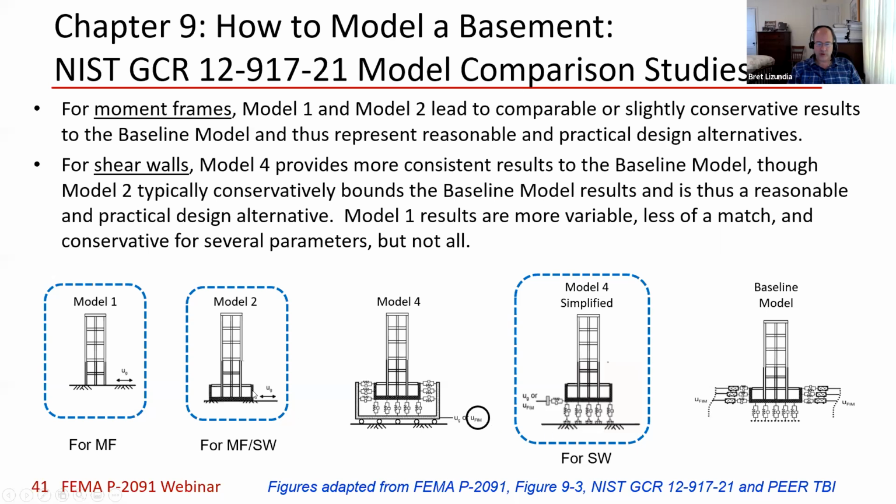One kind of simple thing to take away is if you have a stiff retaining wall, so every basement's got a concrete retaining wall to hold back the earth. So you got kind of a stiff bottom. If you've ever tried to learn about what is passive pressure as you push into the soil and the soil pushes back, turns out you need a fair amount of movement to fully develop passive pressure.